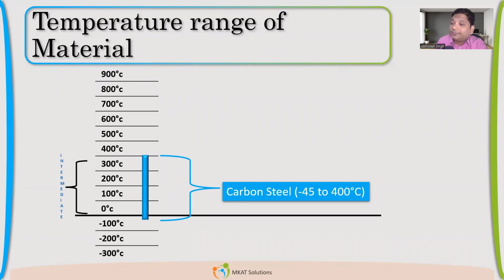Now we have one key factor, which if you remember, the whole material selection will become wide open and clear for you. What is limiting the low carbon steel at higher temperature? Creep. Absolutely right. At high temperature, creep is the limiting criterion. Creep happens in low carbon steel, and that restricts its limit at higher temperature. So now we know a little bit about carbon steel.